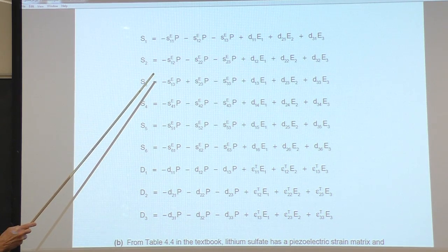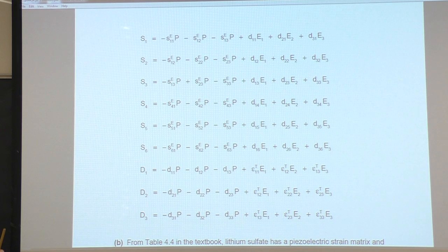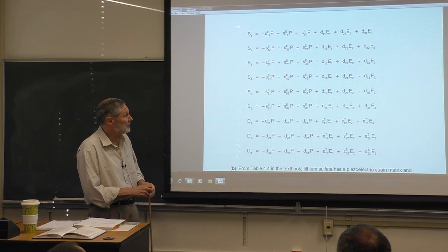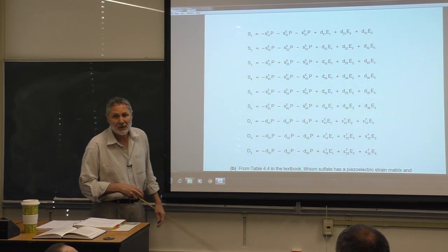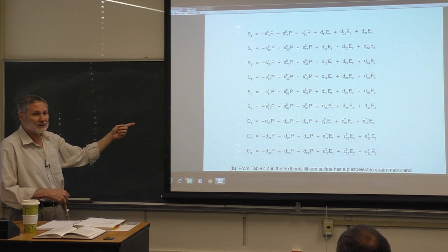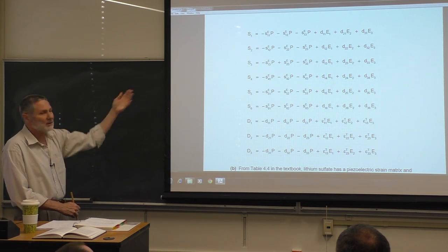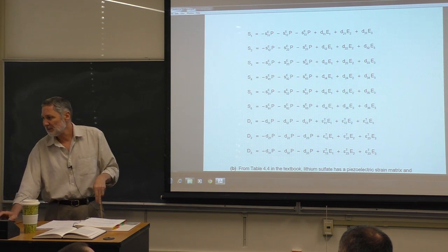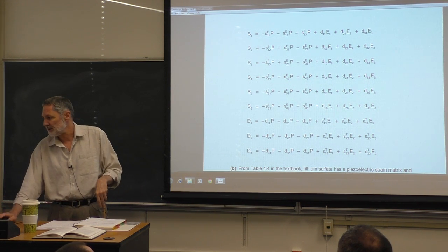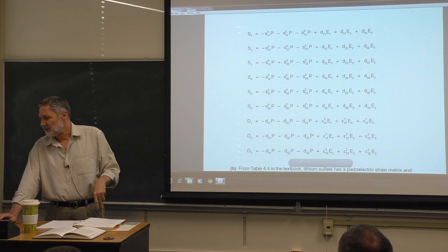We're assuming that there's no shear stress. All the T4, T5, and T6 have been set to 0. And T1, T2, and T3 have all been set to minus P. So they could even be more complicated than this, okay? So we've made that specialization. But it's an unbelievable nightmare, right? But again, we specialize. We look at special cases, and we'll get these to collapse down.